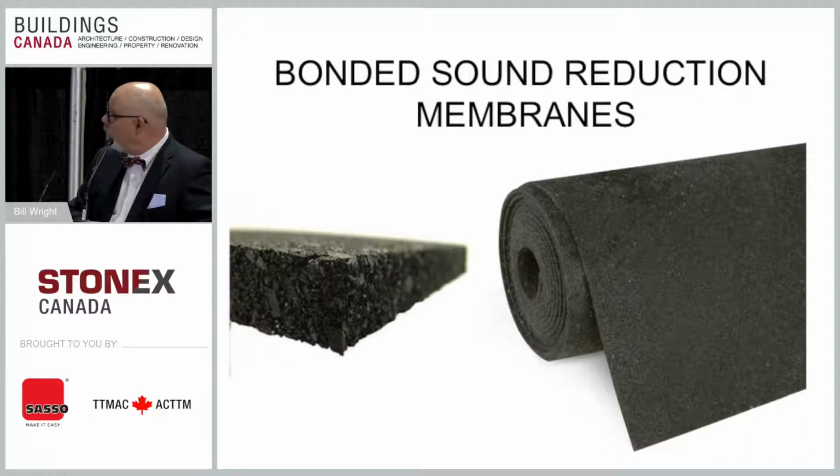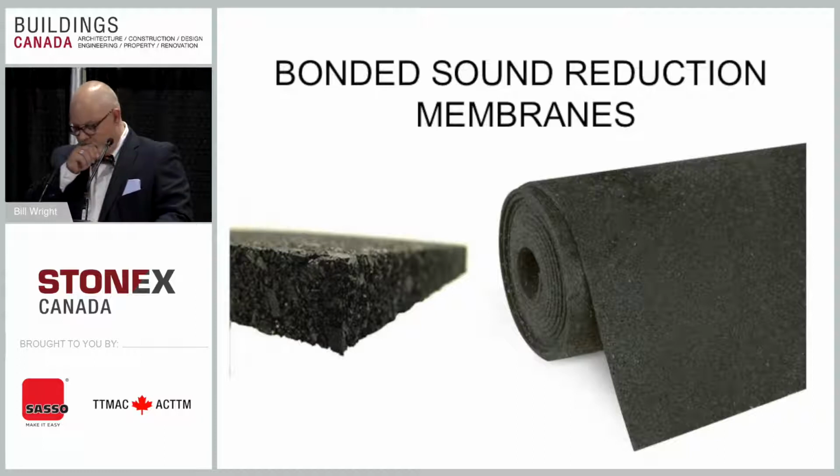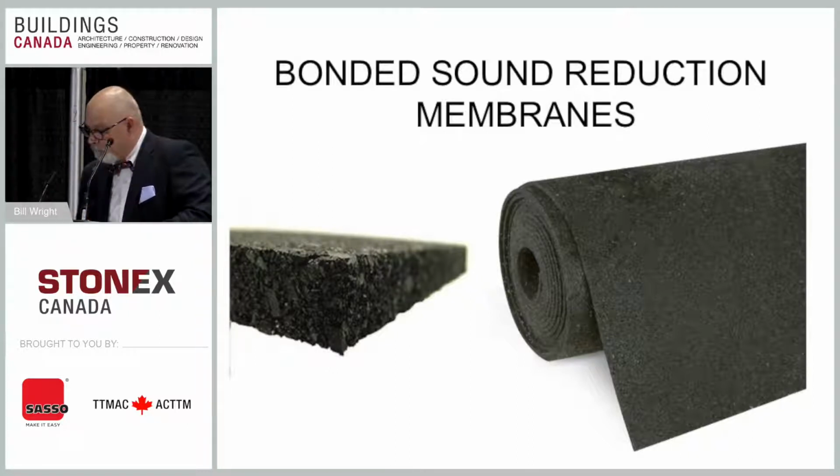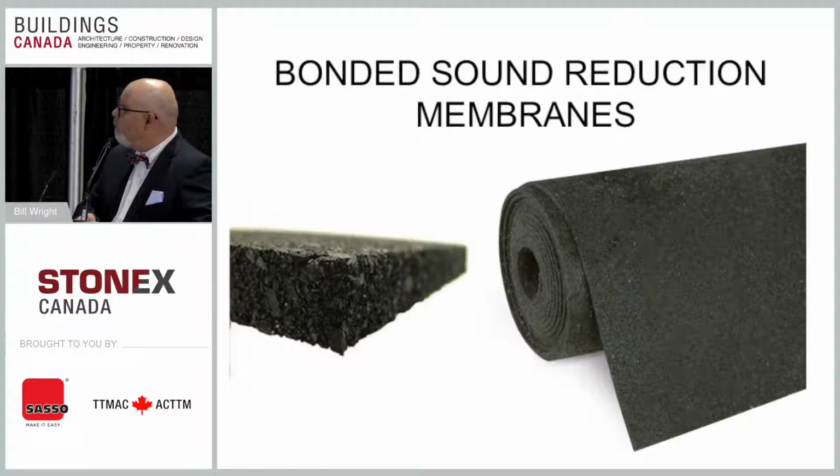Sound membranes. Quite commonly, we'll see something made of a recycled tire appearance, multicolor. Seems to be the most popular thing out there. You see a lot of this used in condominium types of projects. A lot of them have very, very low profiles, so they don't add a lot of great height to the floor assembly. There are standards for them to meet, ANSI A118.3. Most of the brochures will give you an idea of what their ICC rating is in terms of their transmission of sound. Things to consider.